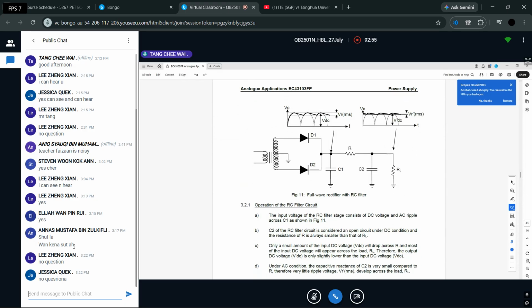This is good for you because now visually you can see what we were talking about earlier, with only one capacitor as a filter. You get something like that, the ripple voltage here at the top. You can quite obviously see that this peak to peak, or the VRMS here, is thicker, or the value is higher, than the one on the right, correct? I circled this. Obviously, that is the purpose of adding in another RC circuit.